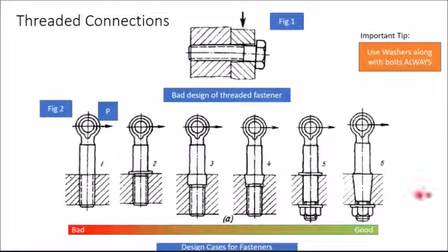In more correct designs 3 and 4, the rod has a cylindrical or tapered section which fits closely in the housing hole and efficiently impedes the transverse rod displacement. Since it is rather difficult to assure strict alignment of the threaded and plain sections, the screwed end must have sufficient clearance. The best designs are designs 5 and 6.